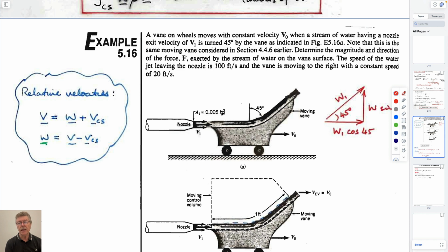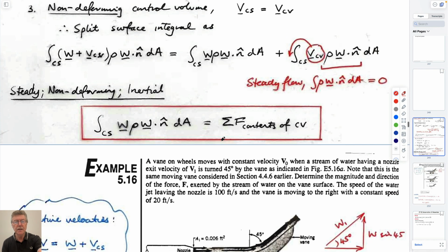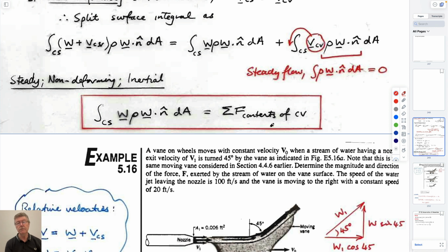And we can use the same idea of what we've looked at now to write the equations in terms of Newton's second law, but now the velocities that we're interested in are relative to the vane velocities, which is why we're interested in the Fire Department of New York fireboat and looking at the velocities coming out of it and coming into it. Everything has to be in the right reference frame. So we'll do that next time. We'll do a more sophisticated version of the moving vane, and then on Friday we'll talk about lawn sprinklers and Pelton wheels when they actually do go around a circle, instead of having that circle be of infinite radius. It's just what we're doing right now horizontally.